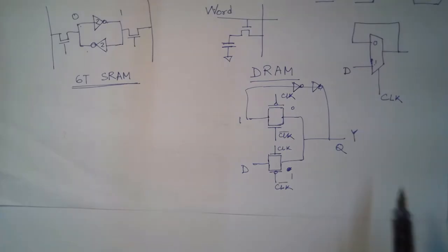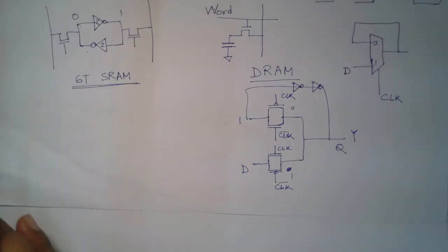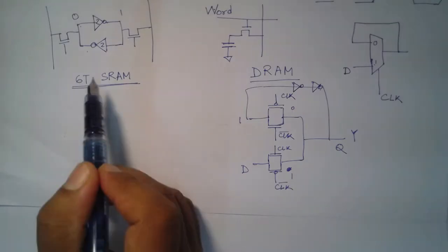So, this is the trade off you need to be aware of, that at one end you have very high speed memory in the form of registers. On the other hand, you have very dense, not so high speed memory like DRAM, but the density is really good. So, you can store a lot of data in a small area, and then there is something intermediate which is SRAM.